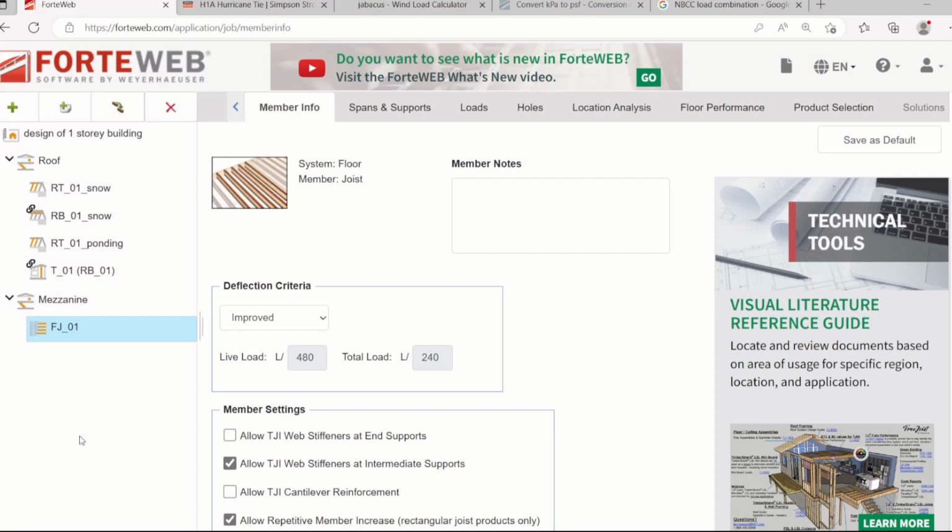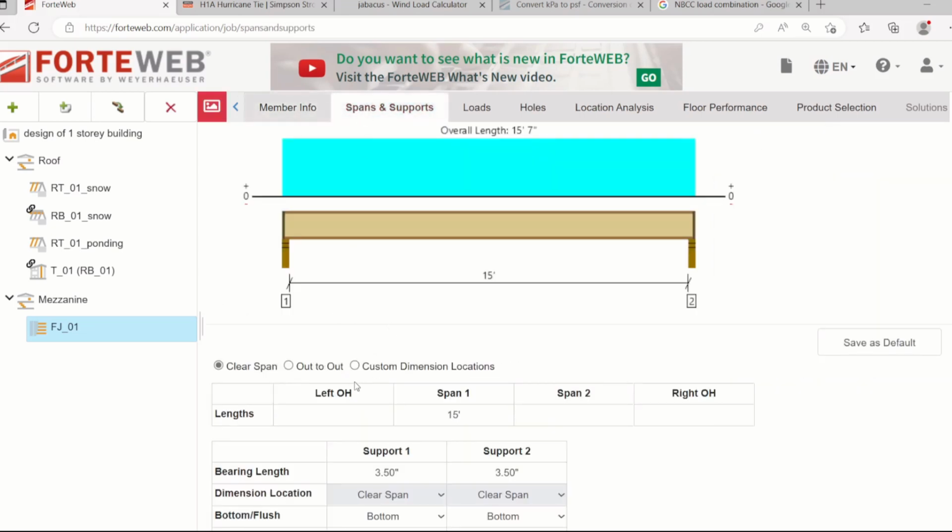If you have different joist, like different span or different orientation, then you rename it with other. So on this one, span was what, 30, but this is out to out, right? And then this one, this is a 2 by 6, so 5.5.